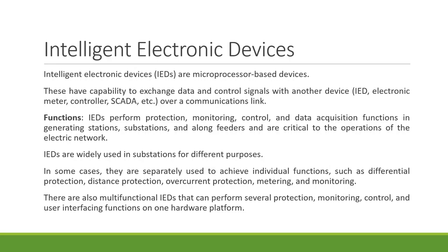Intelligent electronic devices are widely used in substations for different purposes. It is not only one purpose for which IEDs are used. In certain cases, they are used separately to achieve individual functions. It could be differential protection, distance protection, overcurrent protection, metering, monitoring, where individual IEDs can be used.